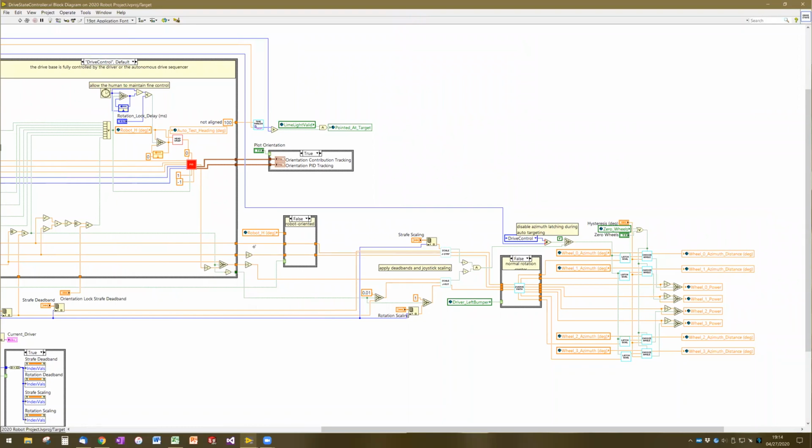We're not going to touch the rotation joystick at all, because counterclockwise and clockwise don't change based off the robot orientation. All we need to do is look at the X and Y commands from the translation joystick. So in robot-oriented, we do nothing. It goes through the Swerve math just as normal.